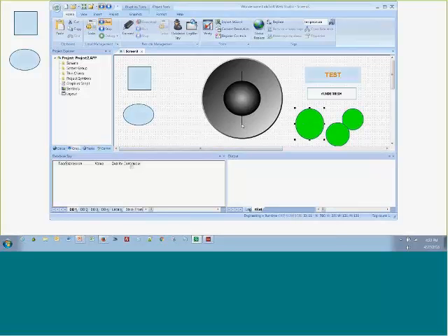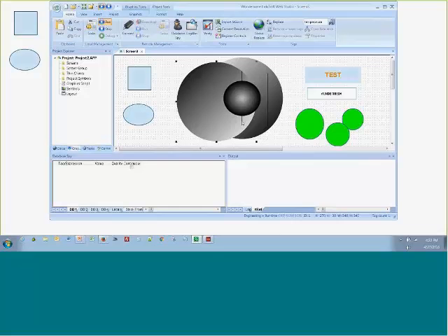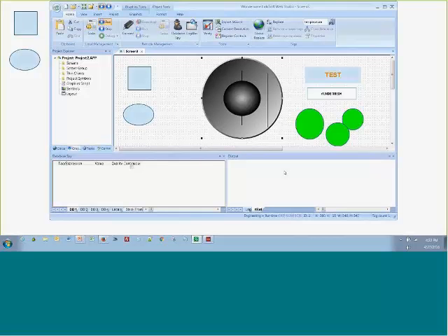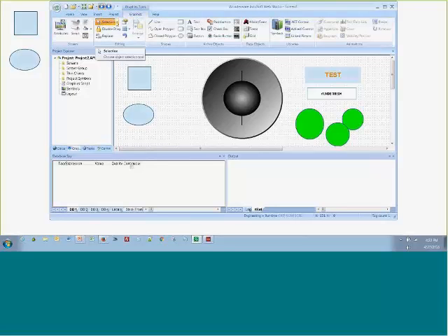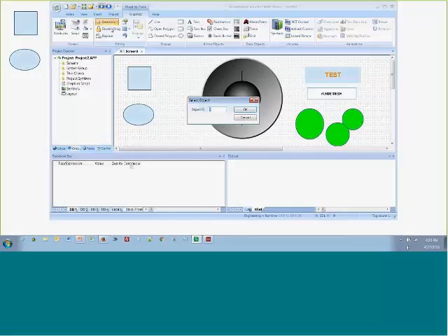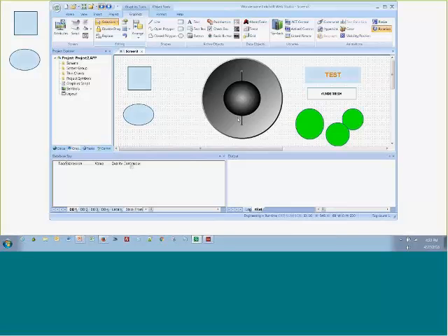So let's say I was delicately configuring some of these lines, and I had moved these into a place where I knew, okay, it was this line, and it was ID number 16. I can actually get to an individual item by doing this. I can go to Graphics, Selection, Go to, and then type in that ID number, and it will select that individual object. Now, how can I click on that because it's behind some of the other lines?